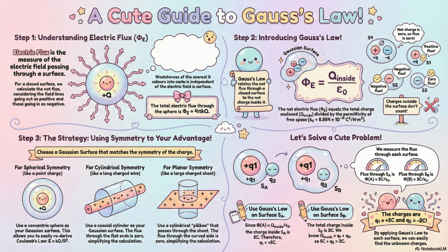Okay, finally, let's quickly touch on the film capacitors. The durable ones. They at least have one really cool feature. They do. Reliability. And what's called self-healing. The metallized film types have an electrode layer that's so thin that if a minor fault occurs, the leakage current is enough to instantly vaporize the metal right around the fault. It clears the short. They sacrifice a tiny, tiny bit of capacitance to prevent a catastrophic failure. They fail gracefully, which is pretty rare in this world. It's the ultimate insurance policy, built right into the component itself.